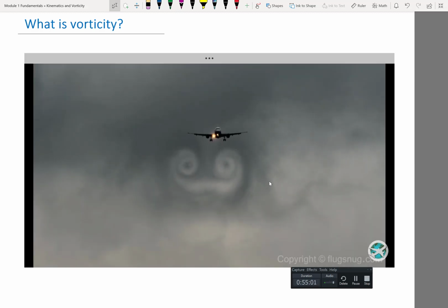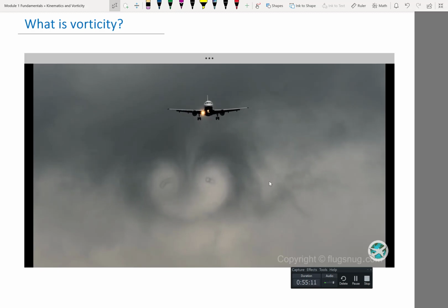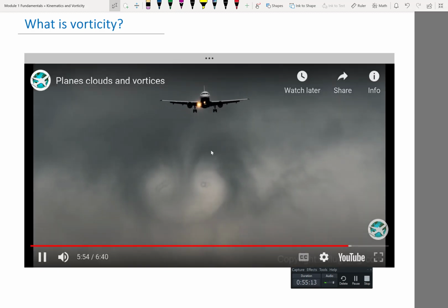If you look at cases like this, whenever you see the flow being fast, because most of the flow is irrotational, and if you go across from one streamline to another streamline, and if the path has no vorticity in it, then you know that whenever the flow is going faster, the pressure is lower, right?